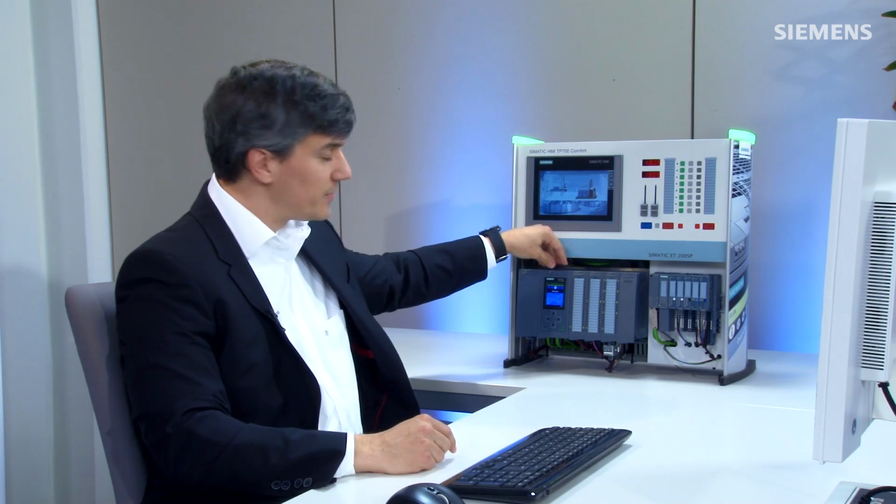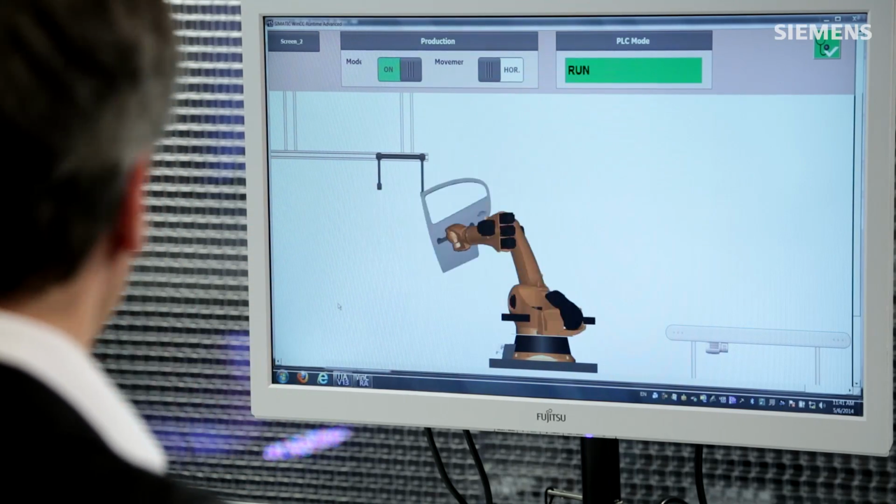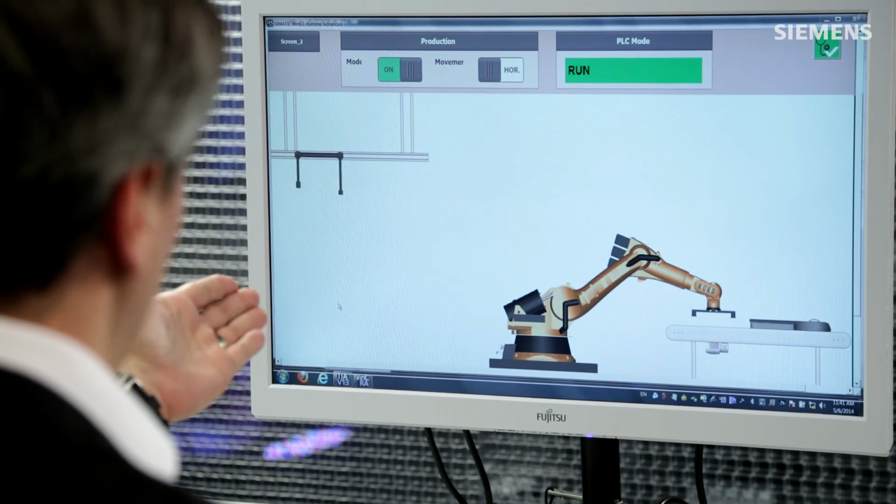As you can see here, I have a 1516 controller for this system, an ET200MP I/O, and an ET200SP distributed I/O, both of which are on PROFINET. If I come over here, I can see I'm virtualizing the 22-inch Comfort Panel for this particular system, and this is the HMI we want to replicate for the new plant expansion.